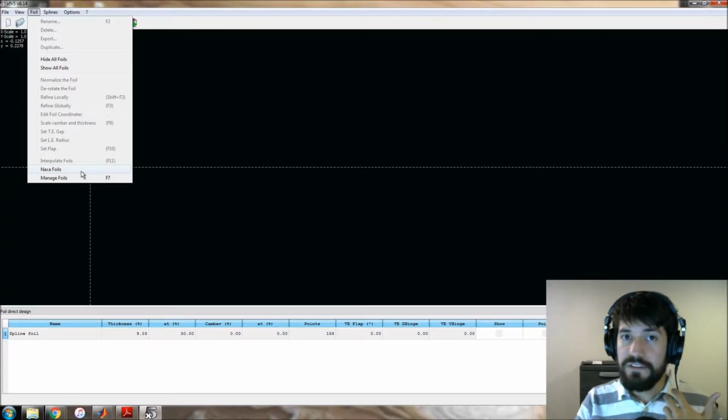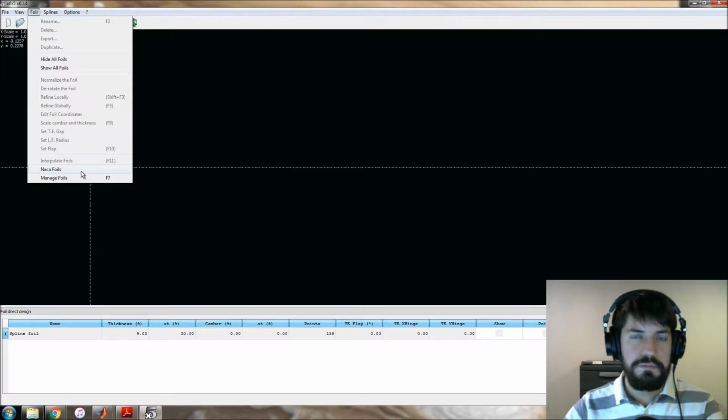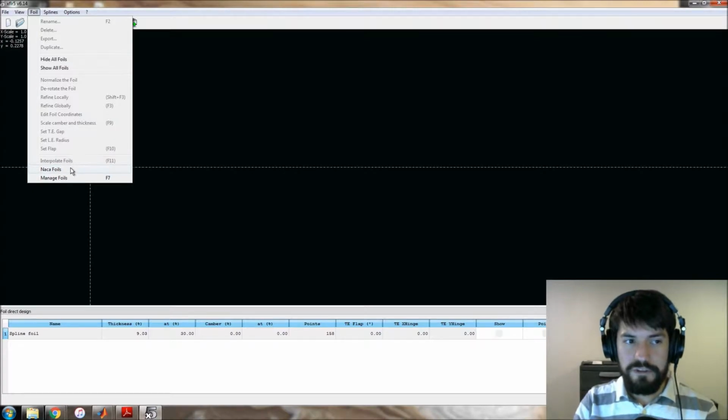For this basic analysis that we're doing, you don't have to go out on the internet, find airfoils, download them, do all that stuff. Because the basic characteristics we're looking at for this first pass of general performance, just for trade studies, it isn't interested in that level of detail. So you can just use NACA airfoils, which you generate on the spot.